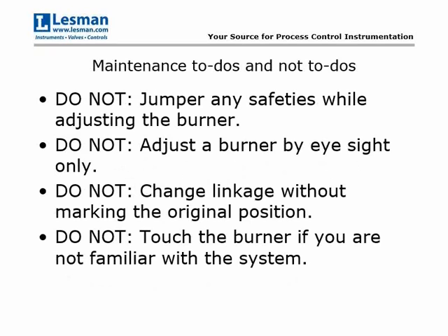All right, let's get into the not-to-dos. So we do not, of course, want to jumper any safeties while adjusting the burner. All these safeties are in place so that we light the burners, we don't launch the burners, and we want to make sure that we keep these safeties intact when making adjustments.